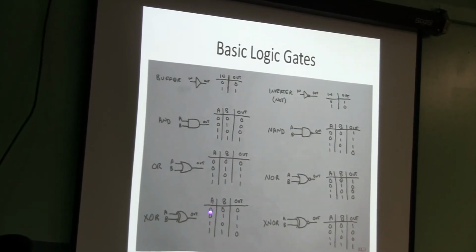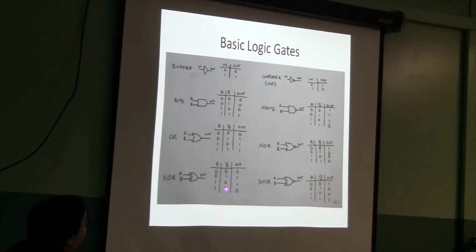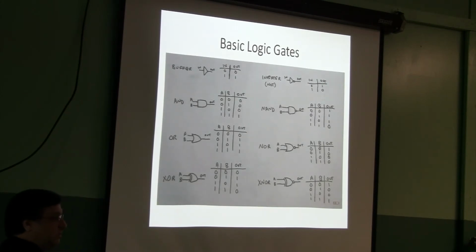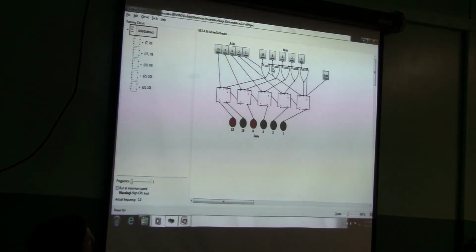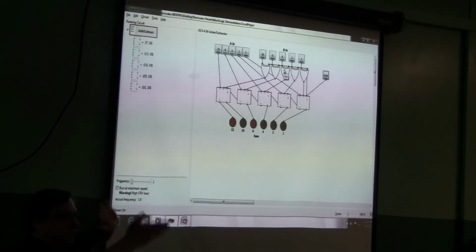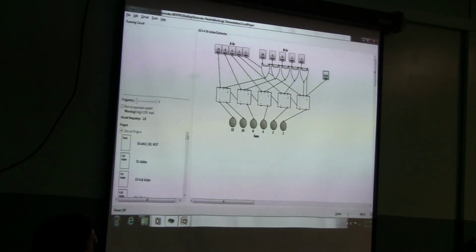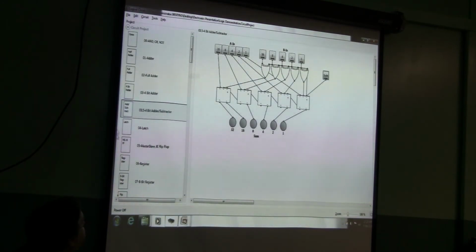But if we turn on our subtraction switch, then the input is going to be inverted: 1 is going to be a 0, 0 is going to be a 1. So an exclusive OR is a very handy little circuit that we can use to have one little selector line and invert our binary number. I just threw this together in like 5 minutes, so I apologize for the crisscrossing lines here. So that's addition, subtraction. That's, at a very, very basic level, how a computer can do math.